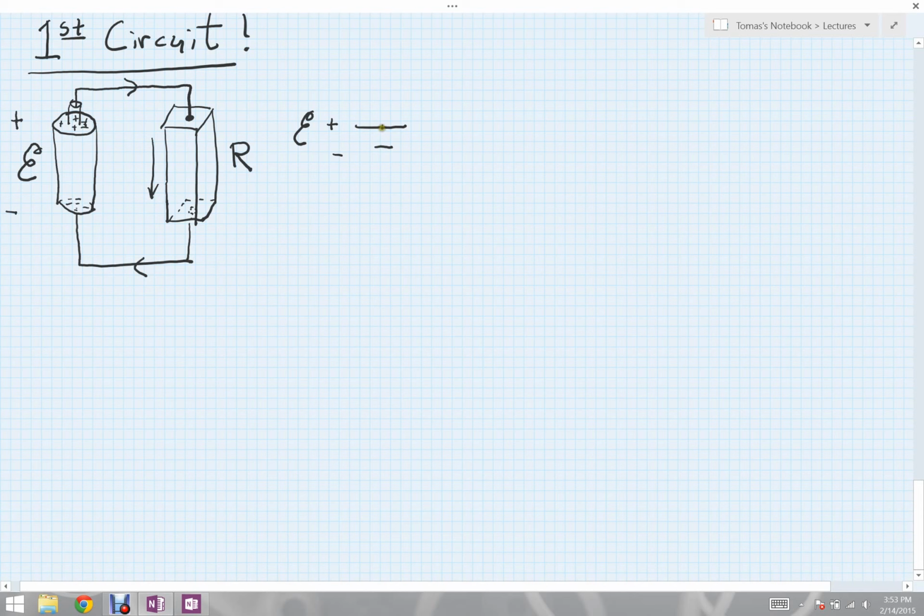The voltage is always maintained constant across the battery. The wires then are represented just by lines, kind of like in my physical diagram. The conducting material that's offering some resistance to the flow of electricity is indicated by a jaggedy line that kind of suggests it's hard or torturous for the charges to travel down along through here. And then finally, my other wire I can just draw as a line to complete my circuit.